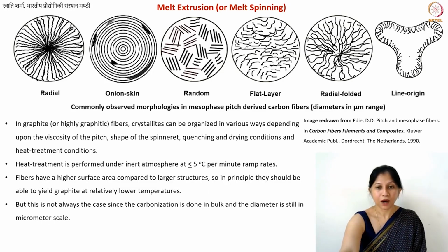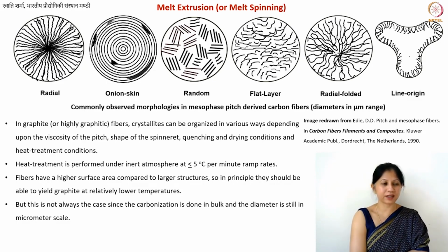So yes, you can make fibers in the microscale, and you can make fibers in the nanoscale. Nanoscale fibers we are going to talk about later on. In principle, during the heat treatment, you should use a slightly lower temperature, as I said, because the byproducts and defects can anneal out more easily. But if it is in the microscale, the effect of surface area is still not that strong.